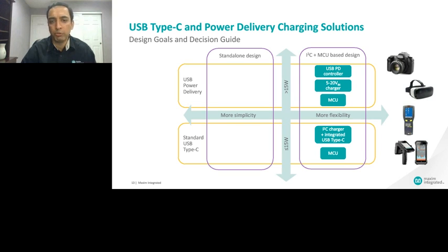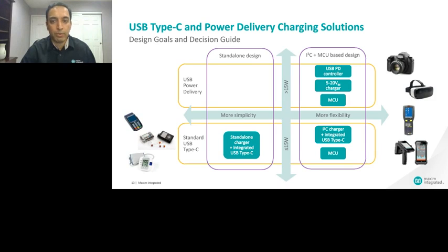This was not possible before, but we now have products on the market which allow you to do that with absolutely no firmware development at all. That includes a completely integrated IC, which has standalone USB Type-C detection in addition to the charger, with no firmware development, and can be configured completely via resistors.